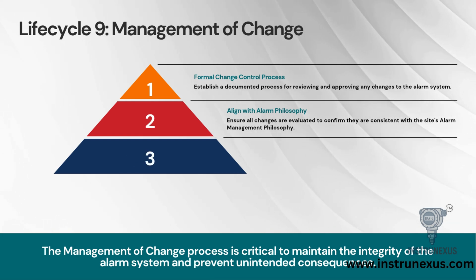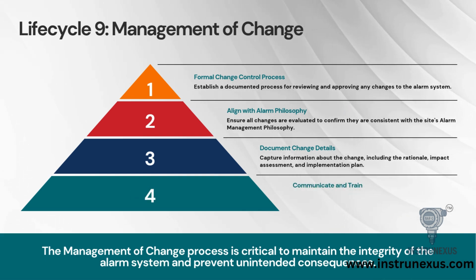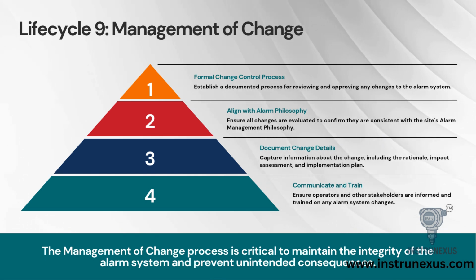We must document the details of the change, why it was made, and the impact it will have. And crucially, we must communicate and train the operators on this change. Without MOC, your clean, rationalized system will degrade back into chaos within 6 months.